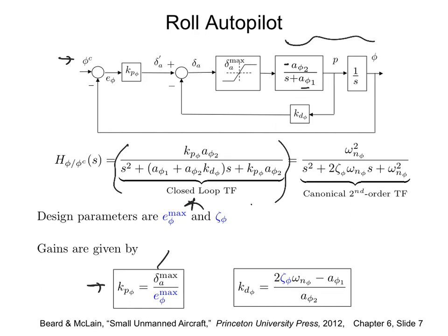That can be 90 degrees. But then your Kp will be really small, so it will be slow. But if you have to go from minus 45 to 45, you go from 45 to 0 and then 0 to 45. You can consider that, and then your e max can be 45. Right? The error max can be 45.